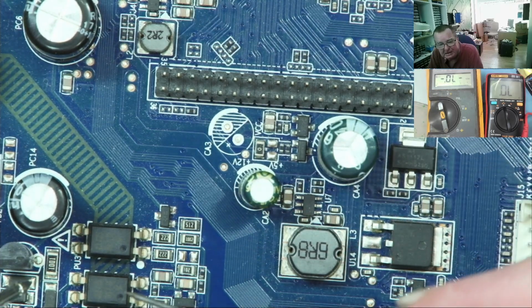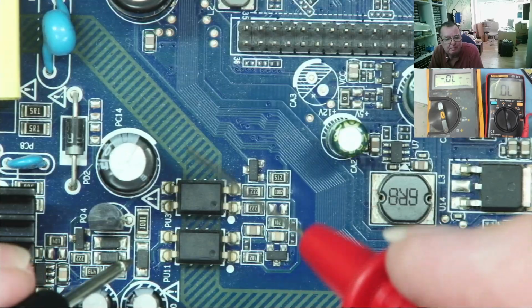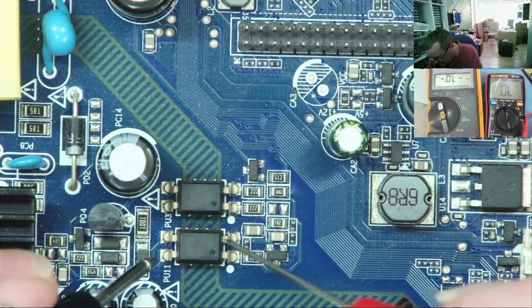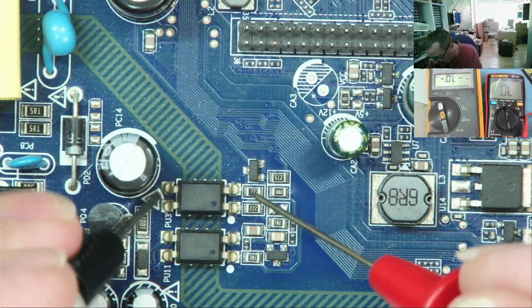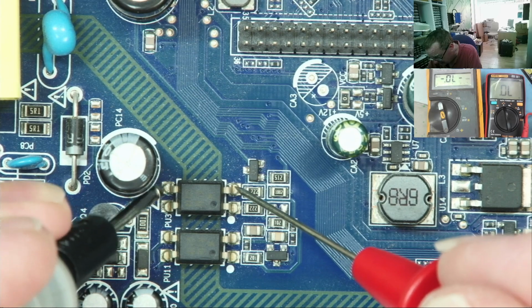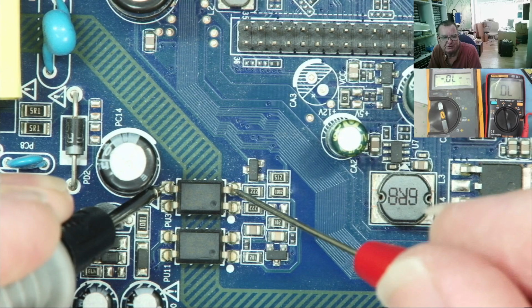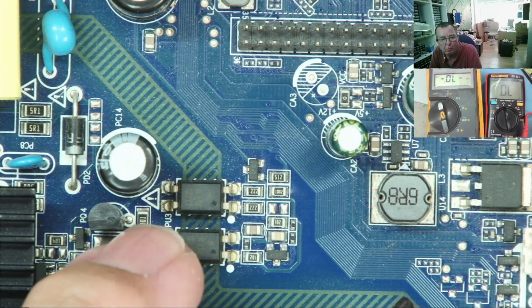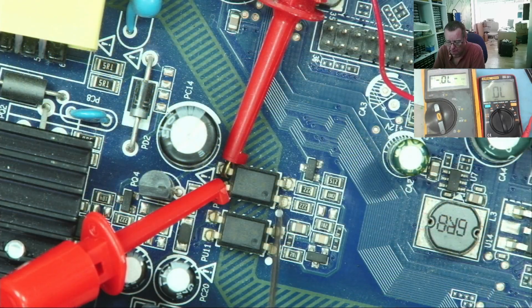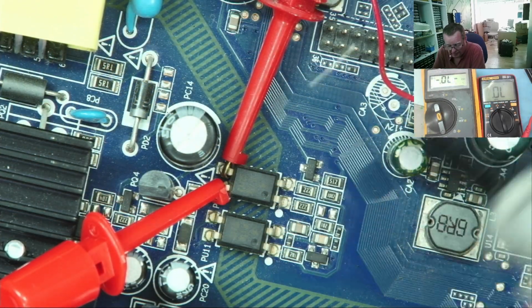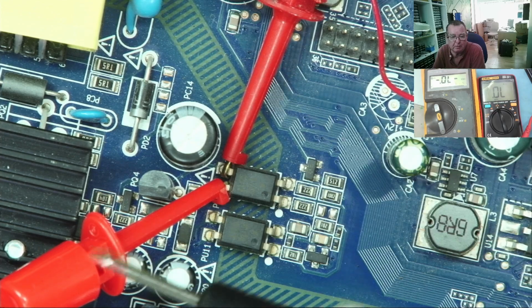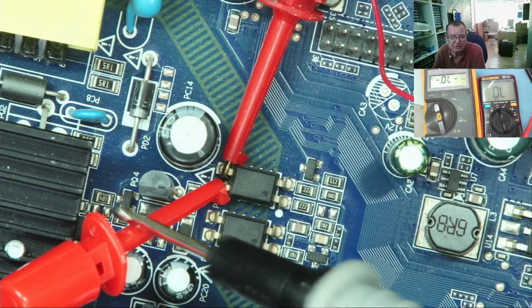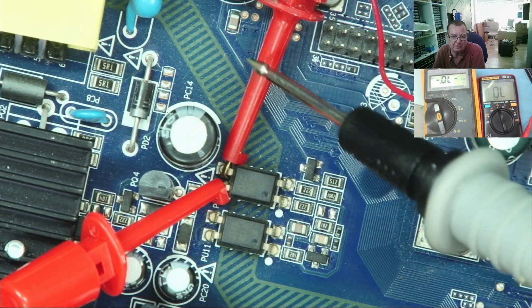and it needs even more hands, you can clip some wires onto here. That's probably the easiest way to do it, unless we're lucky and both grounds are connected together. But they shouldn't be, because it's an opto isolator. So actually, that wouldn't be so lucky. So I'll just put some wires on here. Okay, we're ready. I've clipped these on. These are going to the Aneng. This one's going to the red lead on the Aneng, and this is the black lead.